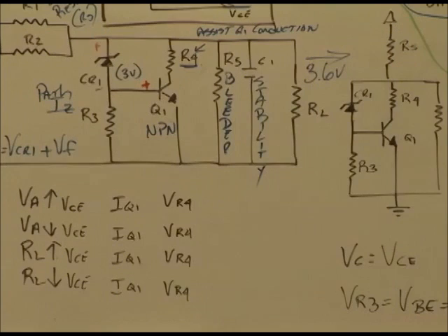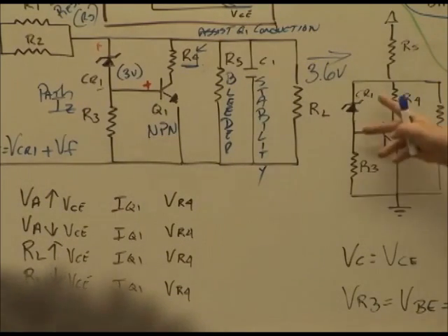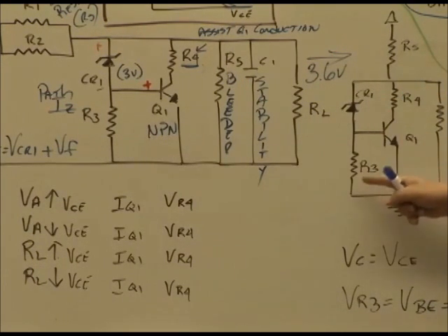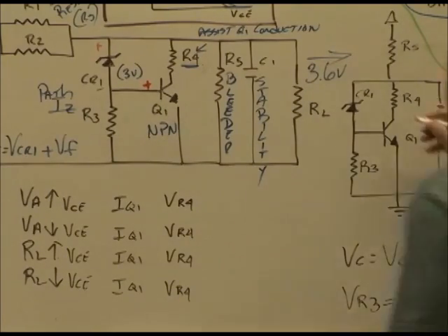What do we always need to remember when the line increases or decreases? I total is affected right now, isn't it? Yes, sir. So just imagine, line increases, the whole circuit, that current is going to be felt to increase. But at the same time, we've got R3 limiting the current to the zener, maintaining that relatively constant, because VCR1 plus this equals the output, doesn't it? Yes, sir. Every one of these branches has the same voltage, don't they? Yes, sir.